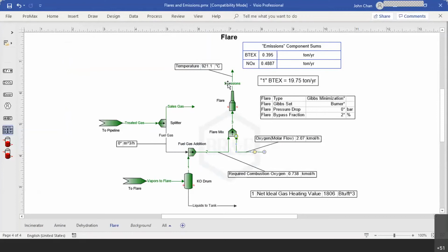From a cost standpoint, the amount of air in excess of the stoichiometric amount should be minimized. But it also has to be sufficient to absorb the heat such that the metal skin does not exceed a certain temperature limit. So typically we do not want the temperature here to go too high. The highest I've seen is about 1800 to 2000 Fahrenheit, and that's approximately 1000 degrees Celsius.